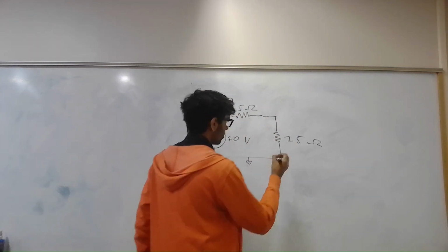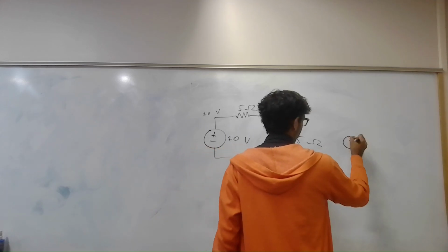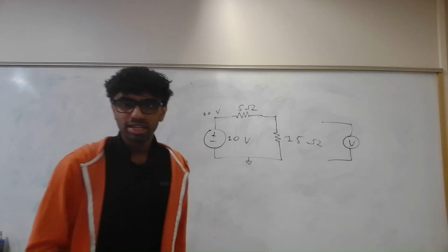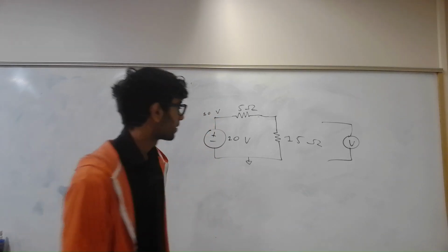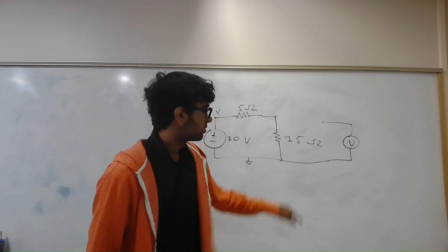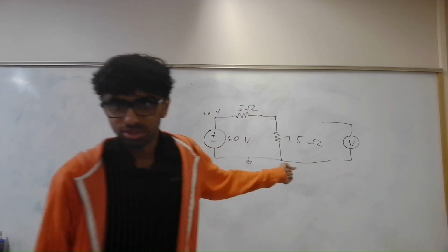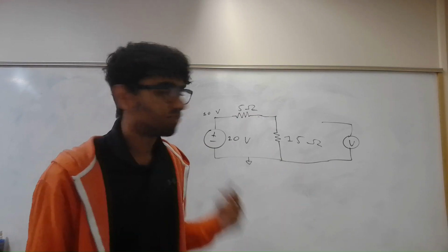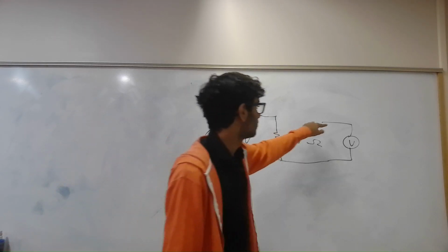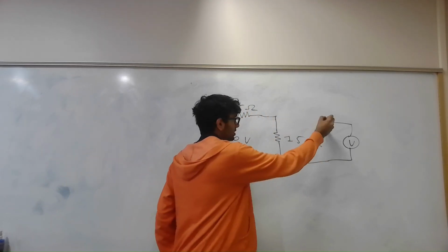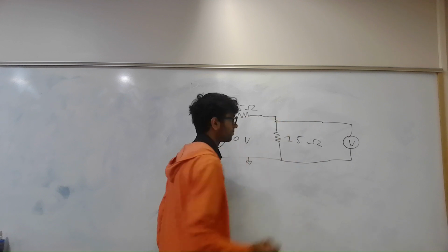So, our voltmeter, it's going to have V, and it's going to have 2 prongs, okay? I need to attach those 2 prongs to something. So I'm going to put 1 prong to ground, okay? So that just tells the voltmeter what 0 volts is. It could, in principle, be attached to whatever my reference is, but the voltmeter is going to tell me the difference in voltage between those two points, okay? And so I'm going to attach the other point right there.